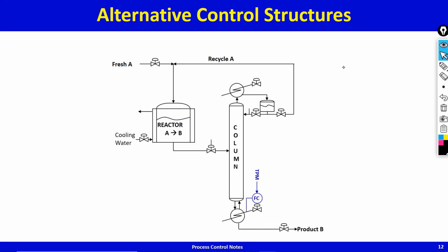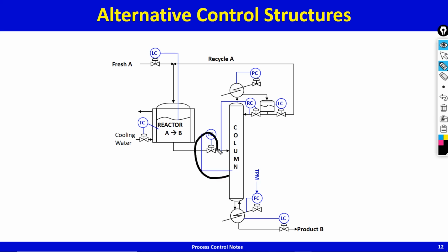You can set production as vapor boil up into the column, and now because vapor boil up is being used for fixing production, the column temperature must be controlled using the feed to the column. Level must be in the reverse direction of flow. Everything else is the same.